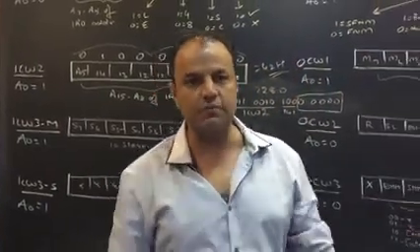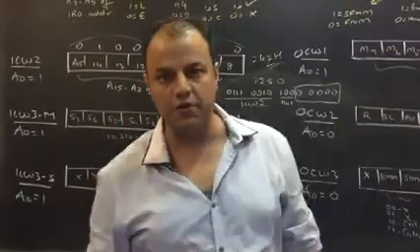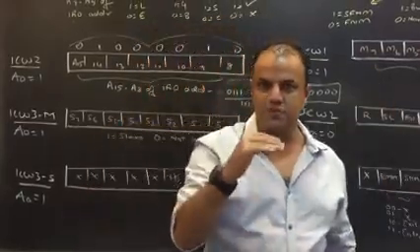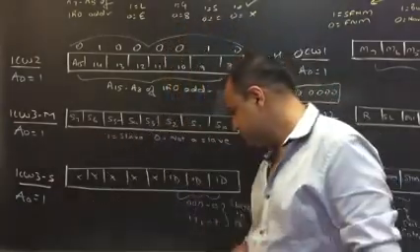8259 is designed in such a way that it will assume those 5 bits to be 0. So if you're starting from somewhere else, that is your problem. 8259 will not work properly in your system. So you have to take care that the ISR address of IR0 has to be such a number whose last 5 bits are 0. Please tell me, did you understand this?